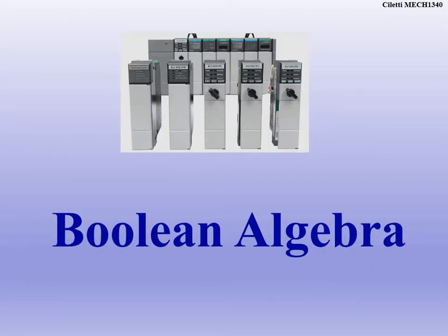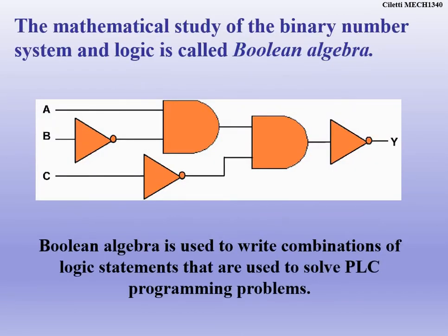Now, many of you guys in digital electronics hated Boolean algebra, but it's really just your basic algebra and simplification. So we were able to take this big old expression here. So, a basic logic circuit here, where we have A and not B ANDed with not C, and then we invert that whole signal. We had to use De Morgan's theorem, break the line, change the sign, that sort of thing. So not everybody's gone through this, but we'll get through a little bit.